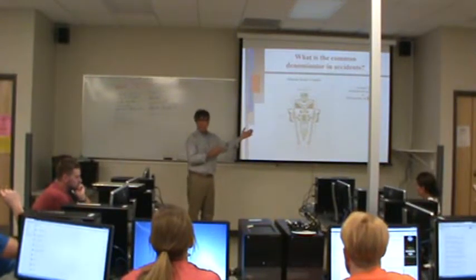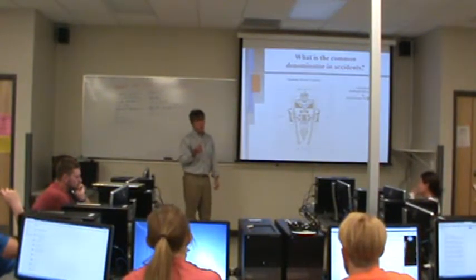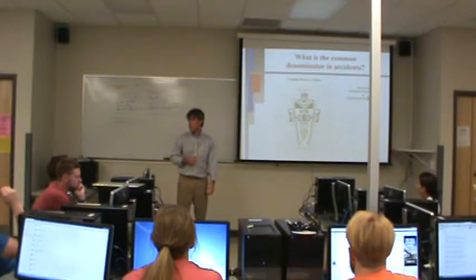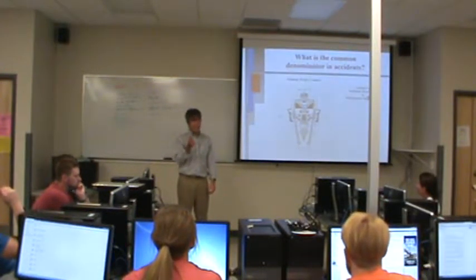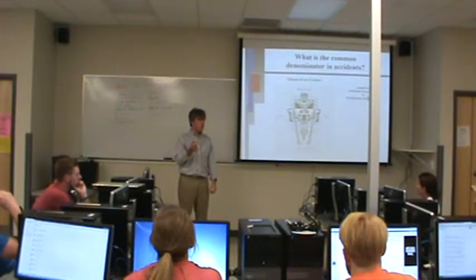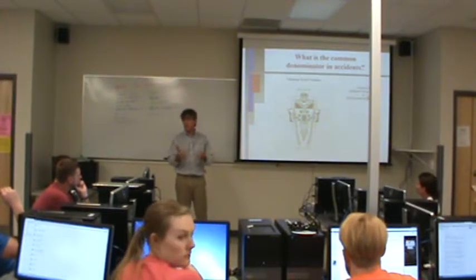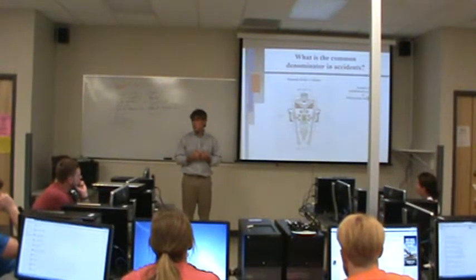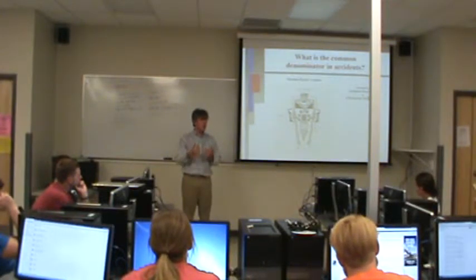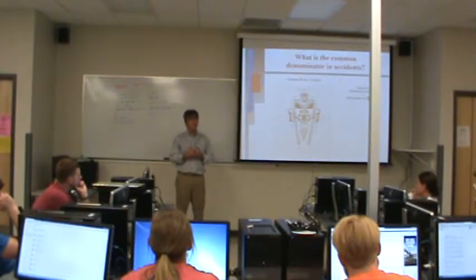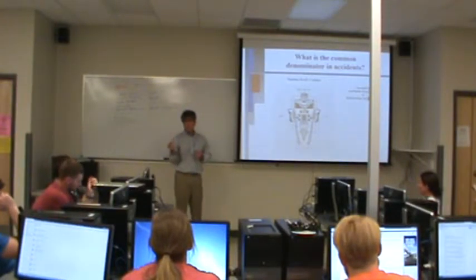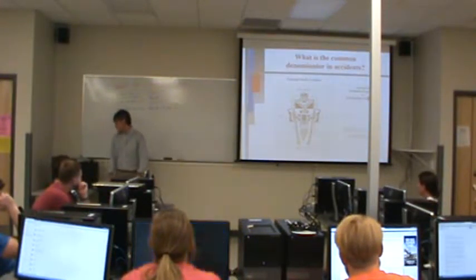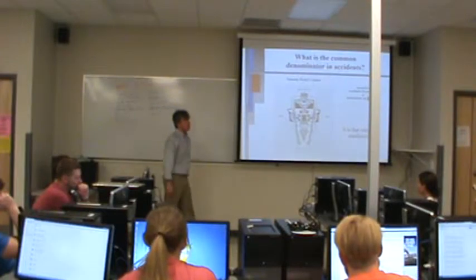Okay, why are they moving fast? It's so that the job that the machine has to do can be done, right? But what does the motion of those rocks represent? Think back to physics. Remember the equation for kinetic energy, 1/2 mv squared? That rock has kinetic energy, right? And why did that rock have kinetic energy? It had kinetic energy so the two rocks could knock into each other and break apart. If it knocks into you, what has happened? It's been misdirected, right? The goal was not for the rock to hit a human being, it was for the rock to hit another rock. And so energy being misdirected is what would cause a problem. Does that make sense? In fact, the common denominator of all accidents is that energy is misdirected.